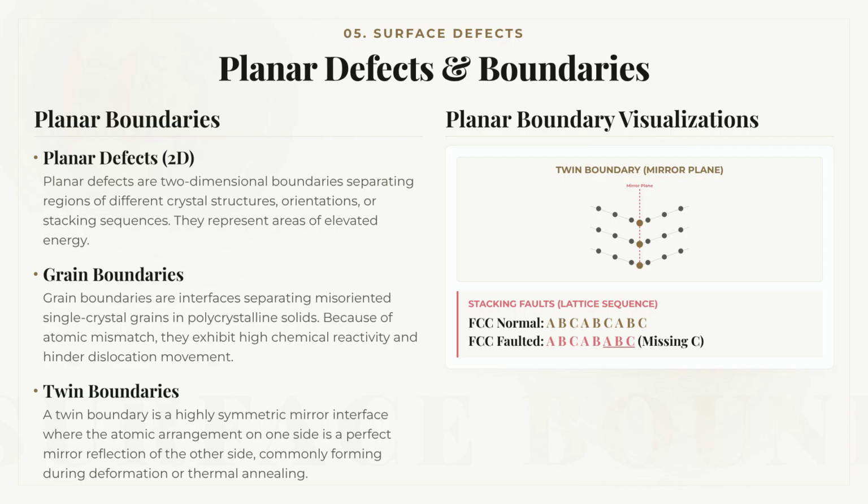Another important surface defect is the stacking fault. To understand stacking faults, let us recall the arrangement of atomic layers in close-packed structures. In a face-centered cubic crystal, the layers are stacked in the sequence A, B, C, A, B, C, and so on. In a hexagonal close-packed crystal, the stacking sequence is A, B, A, B, A, B, and so on.